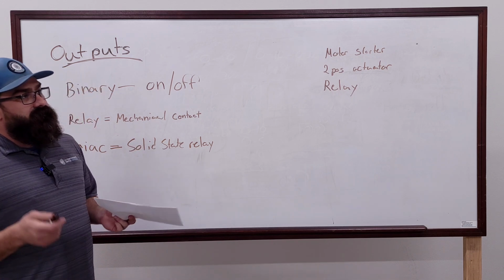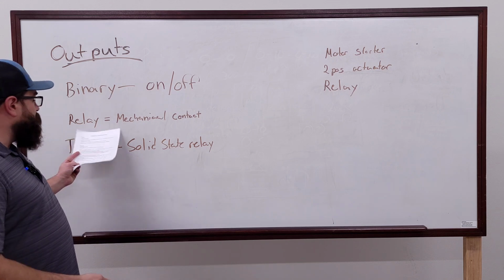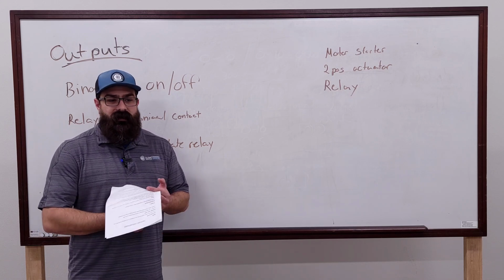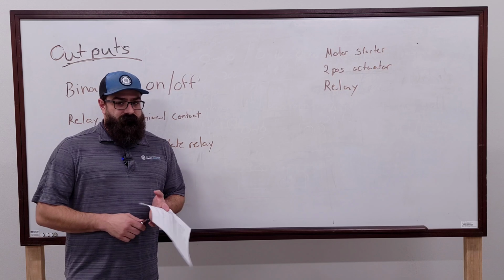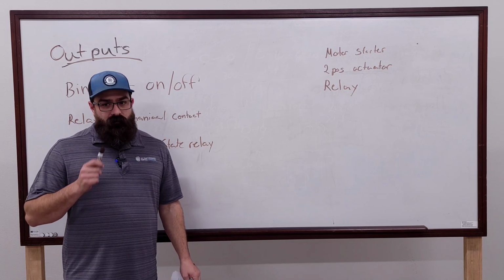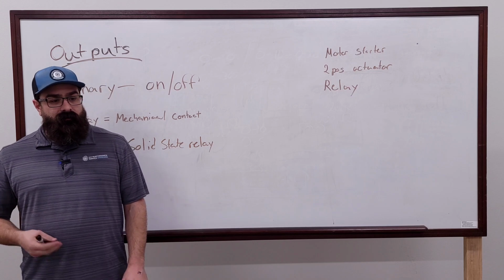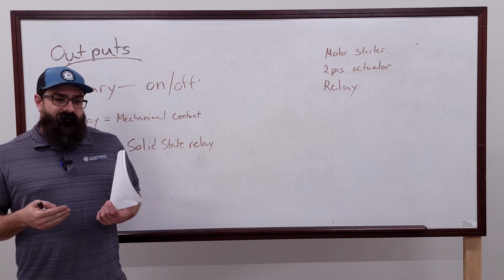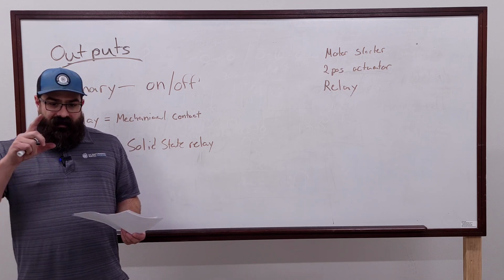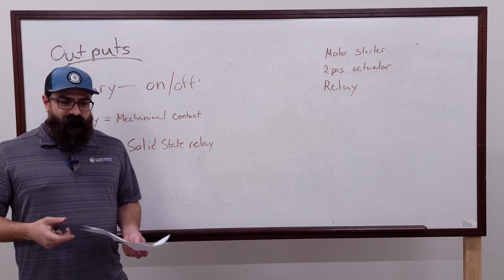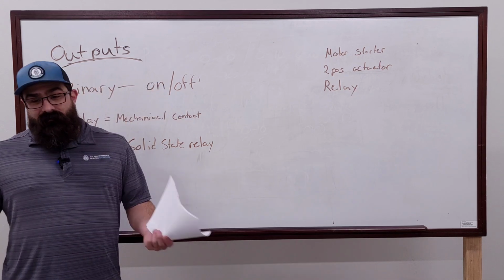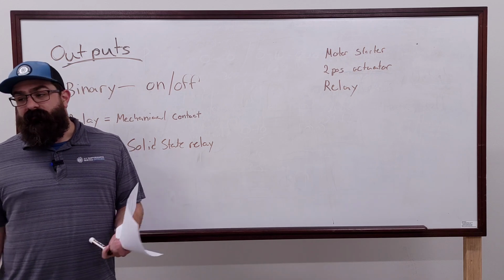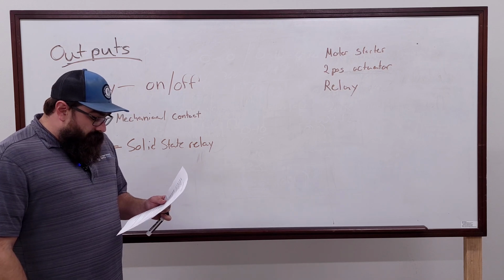The one benefit of a Triac over a relay is the speed. They're instantaneous, like milliseconds, way down there in their response time. So if you're doing something that's really quick, where you don't want any kind of dwell when you command it, it's a Triac. They're fast, because all it is is opening up a silicon gate. It's not like an actual wait for the spring to compress and all that. It's way faster. Nothing we do matters in that because we're not doing process control and stuff like that, but it is a benefit of them that I just wanted to touch on.